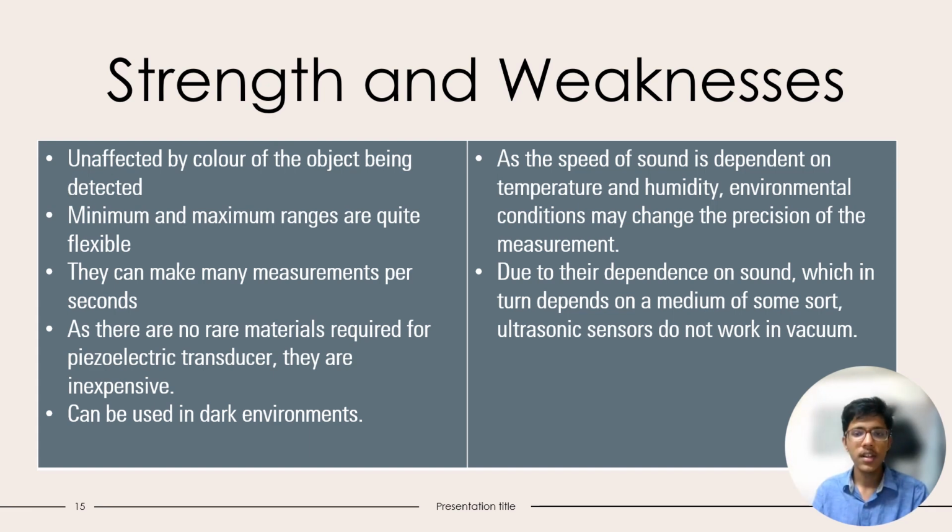Now the weaknesses. As the speed of sound is dependent on temperature and humidity, the environmental conditions may change the precision of the measurement. Also, sound is dependent on a medium of some sort, so ultrasonic sensors do not work in a vacuum.